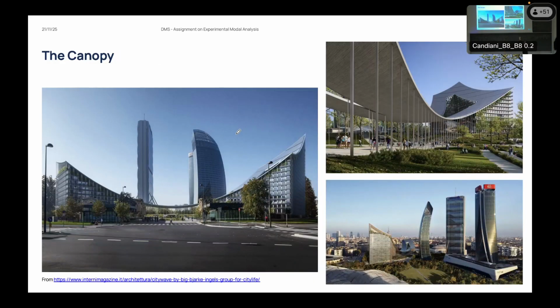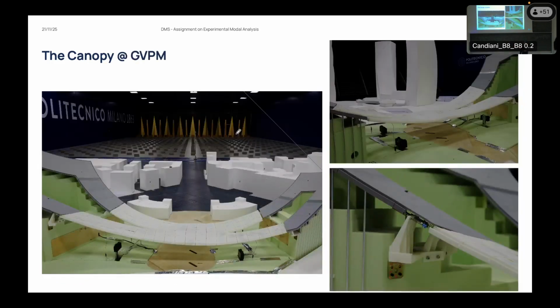So the columns that you will see once they complete it, remember that they have no structural role in the behavior of the structure. They will be just to embed some dampers to damp out the vibration, or be used as channels for water to be removed from the roof. That's the reason why we don't have columns here. Everything that has a structural role in the full structure should be here, because otherwise you are changing the stiffness, okay? So in this case, since the columns won't play any structural role, the columns are not reproduced in the elastic model.